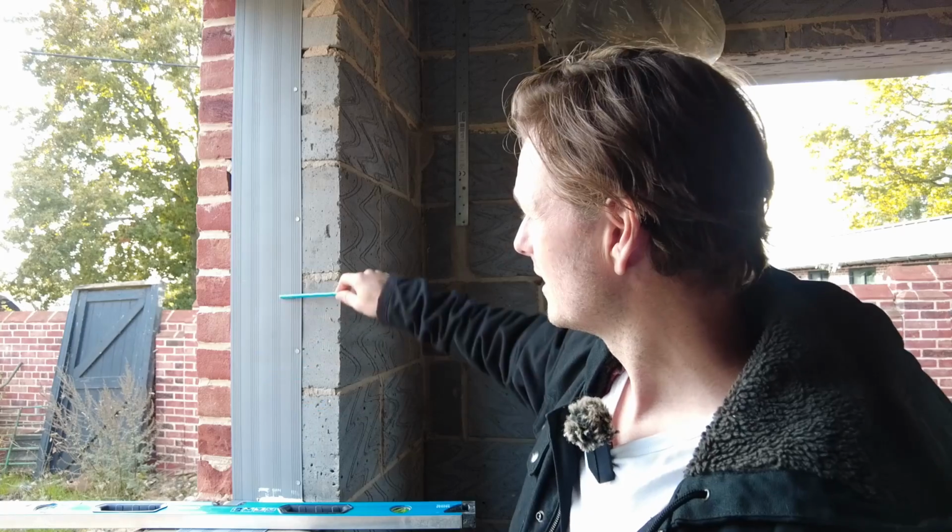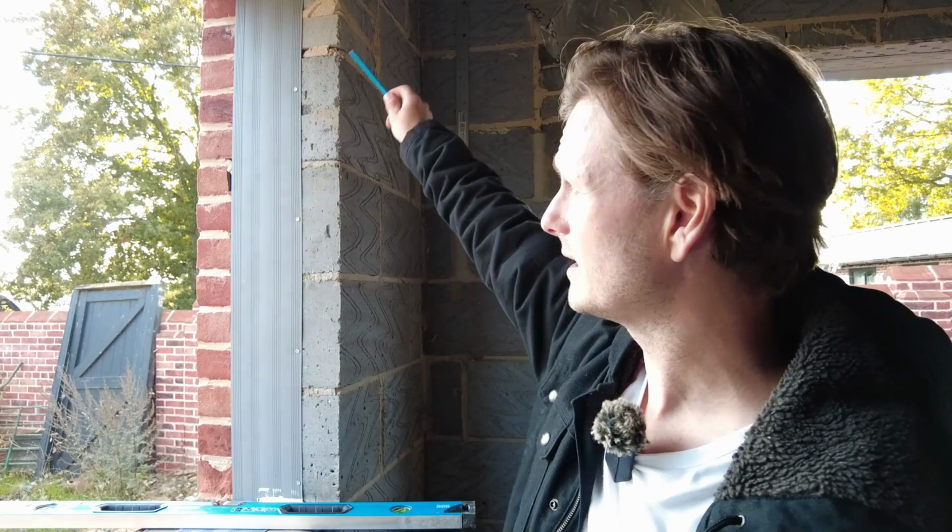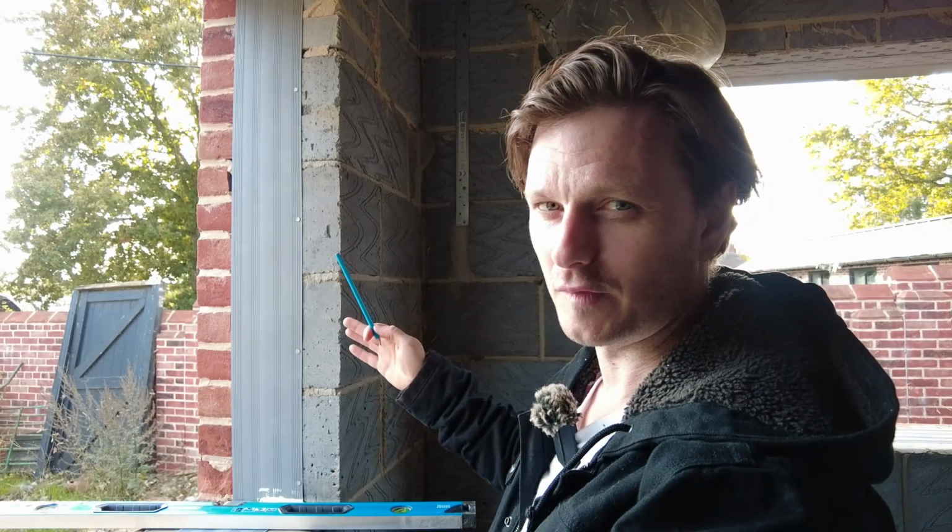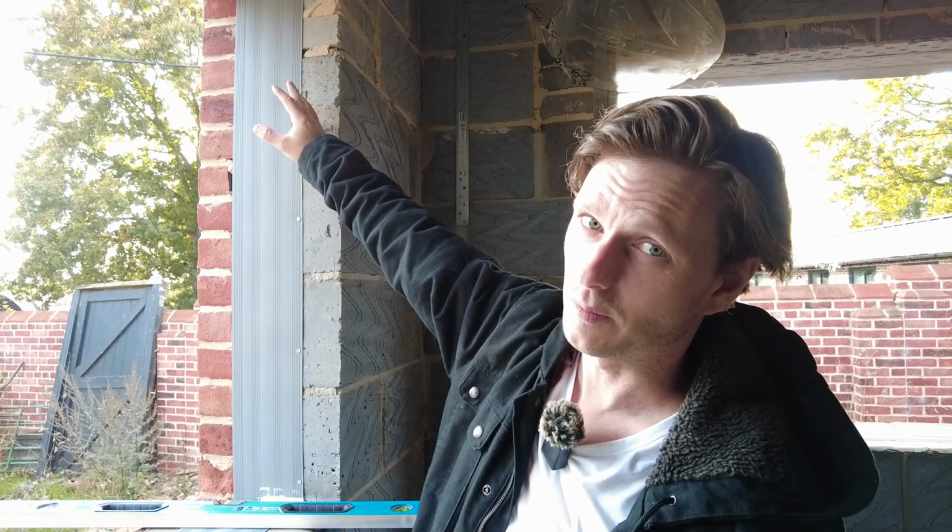Now pay attention, because this is where it gets difficult. You're going to have to do some maths. So you take the smallest measurement on any plane. So this one, this one, this one, the smallest out of them measurements. And then for aluminium windows, for this size at least, you're going to take away 10 millimeters from that measurement. That is going to give you a gap of 5 mil each side, basically. A little bit more, where obviously it's a little bit bigger.